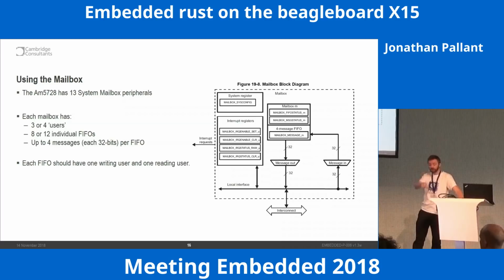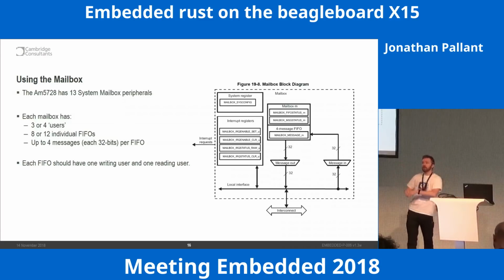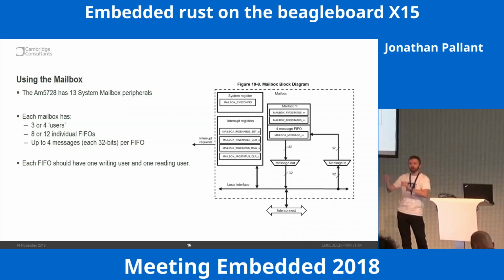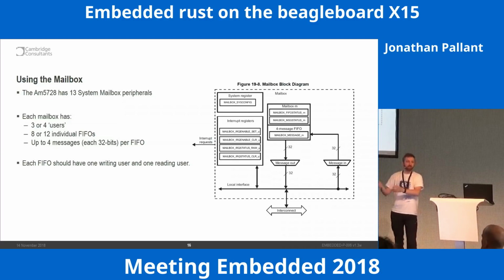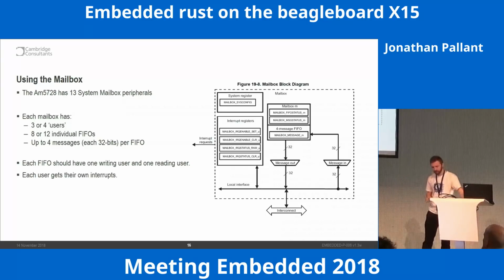And the idea is every FIFO should have one reader and 1 writer. If you have 2 people checking for the mail, then you've got a race hazard. And it's impossible to say who's going to get there first. And the other processor will go, oh, I saw the flag up and I went outside, but the mailbox is empty, crash. So you have 1 reader and 1 writer.